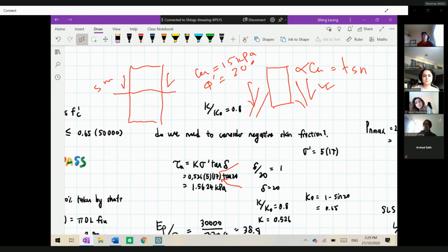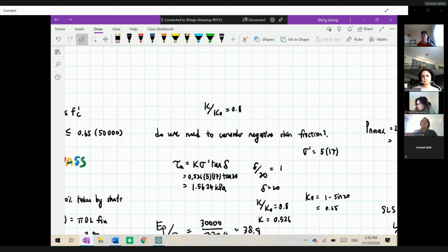Soil consolidation takes place because of the dissipation of the pore water pressure. So that is a drained phenomenon. And if it is a drained phenomenon, to calculate this downdrag we have to use the drained properties. That means the frictional properties would be very important. Okay, now how do you calculate that one? If it is a frictional material, how do you calculate the resistance around the shaft? What equation should you be using?